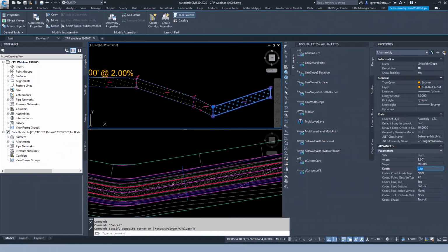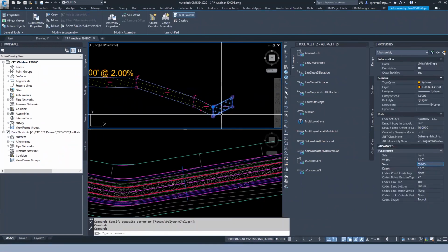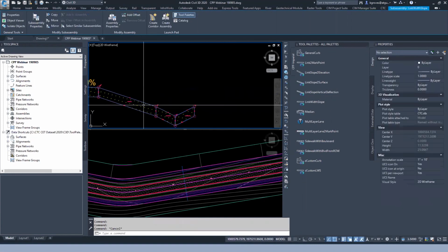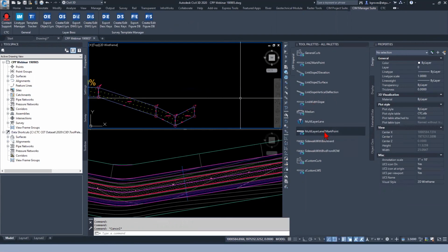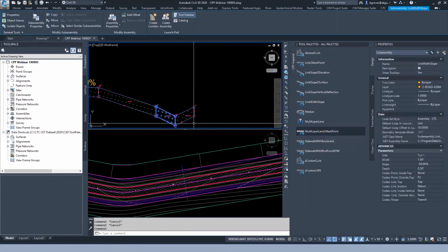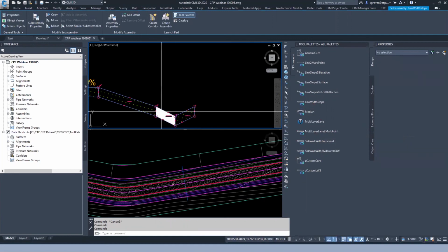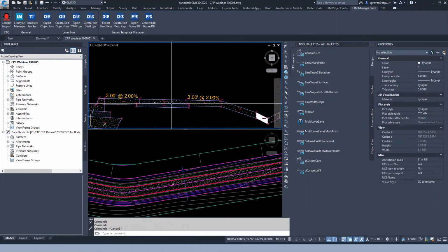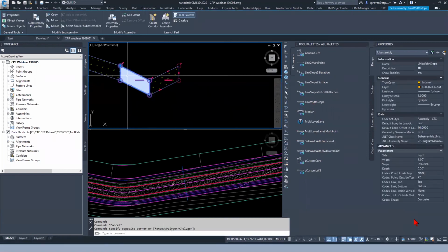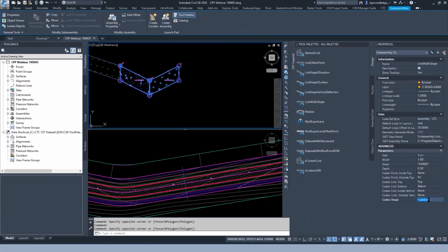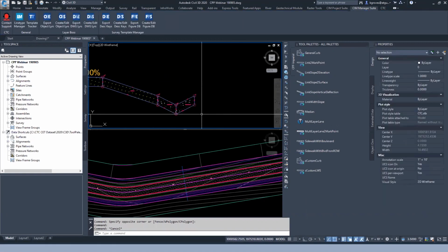So I'll do this one instead of that. We'll go with that. We'll get in another 3-footer here at that 33%. And maybe, so if we're going to do this really, really deep spot here, maybe this is concrete. This isn't topsoil. There, to make it look nice, I'll use the sidewalk code instead of the concrete code. And now magically, our design is going to compute these quantities instead of being a grass material.